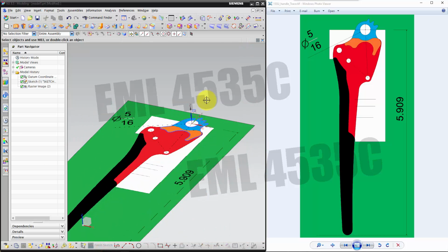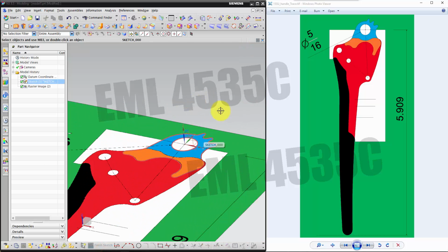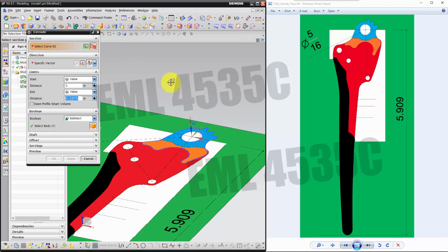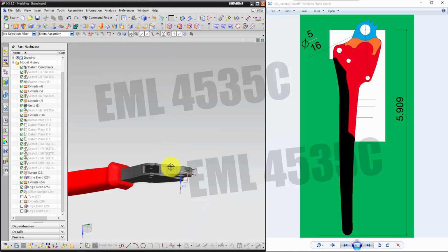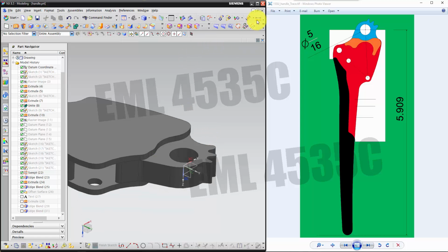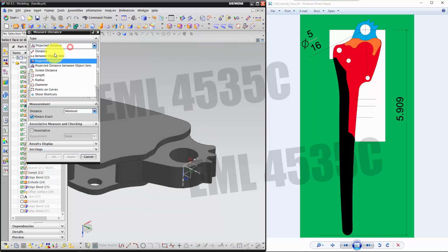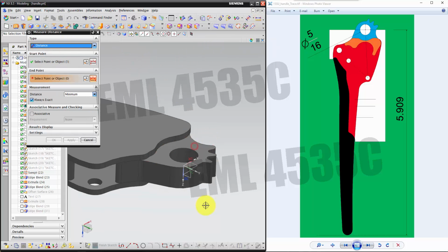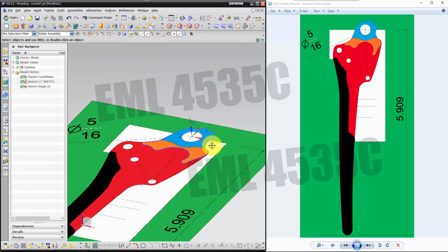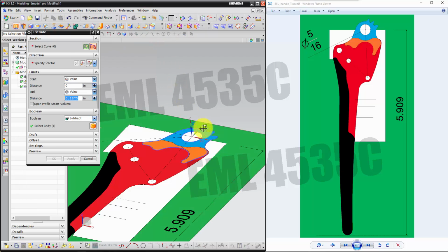Okay, now from here, we've just finished the one sketch. Then you can extrude this portion, and the distance you can measure from the part I gave you. So there's a measurement tool, distance between the top face and the bottom face, a 1/4 inch. So it should be extruded.